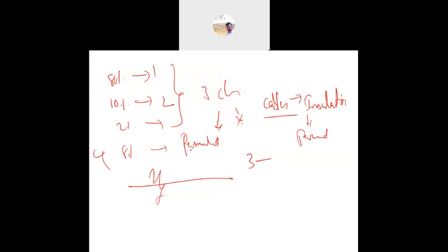In cables, automatic reclosers are not used, because if a cable has a fault it is mainly because of insulation failure. Insulation failure is a permanent fault, not transient in nature. That is automatic reclosing.